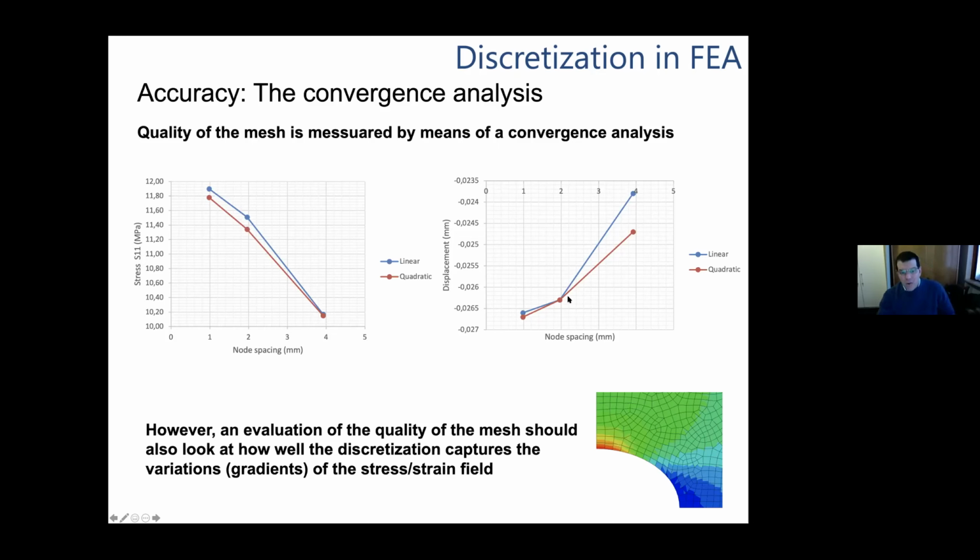So a convergence analysis is a good practice. But an evaluation of the quality of the mesh should also look at how well the discretization captures the variation of the gradients of the stress-strain field.